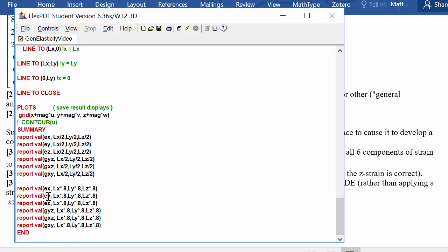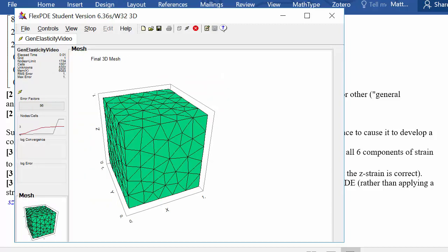To do these sorts of things, let's take contours. So we'll go contour. I think the syntax for this is GXZ. And then you need to say, I think, on Z, and then you can give a boundary. So Z equals LZ over 2, I think should work. Yeah, if that was a syntax error, then it would have caught it before the code actually started.